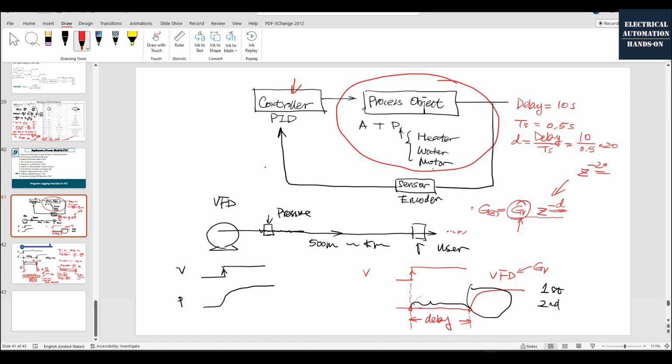And again, this is purely the transfer function, a first order or second order transfer function. But once we see these things here, that means this entire transfer function has the delay, has a lagging feature behind. And here means how many times of the sample time. Just to keep in mind, this D doesn't mean seconds.